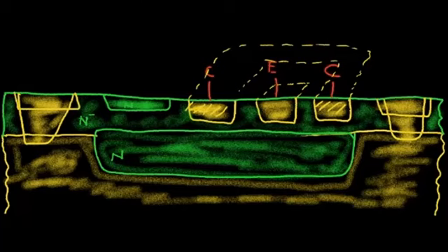So when this emitter base junction becomes forward biased, we emit holes into this region. And most of these holes will diffuse over and get collected. Actually, there's a built-in electric field at the upper edge of this buried layer, and I'll draw that here, pointing upwards.